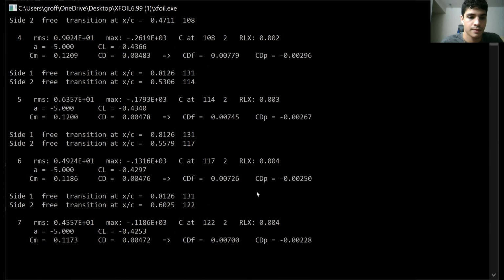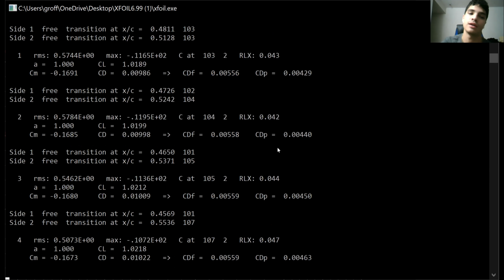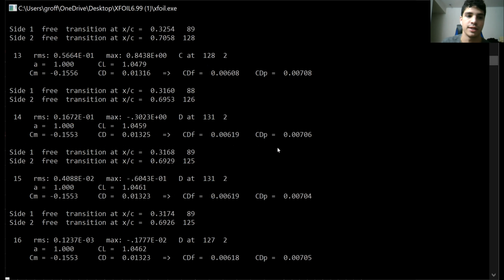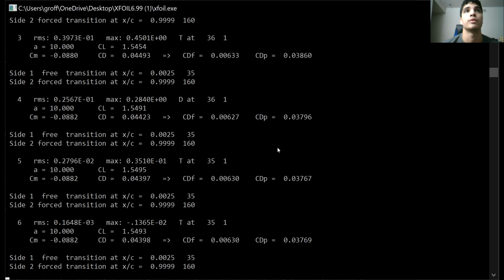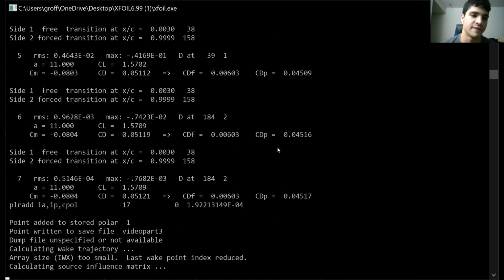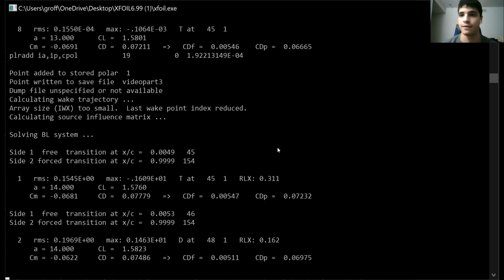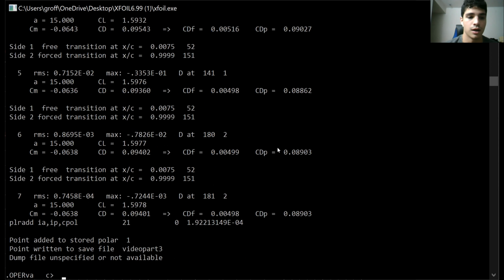And some angles with these flaps are not going to work, so you have to kind of just go with it. Xfoil should tell you, if you read through the data, what angles it's just not going to converge at. So you may have to play around with that. Once you pull it up, you'll see which alphas don't work. Like for the 20-degree flaps, I know that -5 doesn't work, -4 I don't think works, -3 works, but -2 doesn't converge. So it just doesn't include that data. I think this one's done.